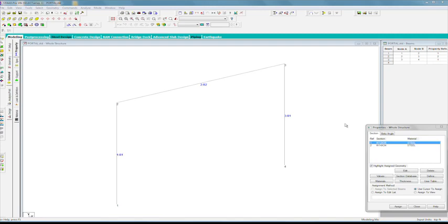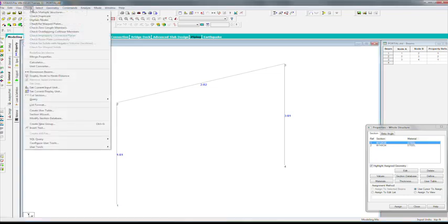Occasionally it's important to be able to change working units. You recall we're working in feet units, but in this case our horizontal member here, the length of it is really going to be less than from center to center because of the width of the 2 columns. So we can change working units simply by going to this little icon and clicking on it, or go over to Tools, Set Current Input Unit right here.